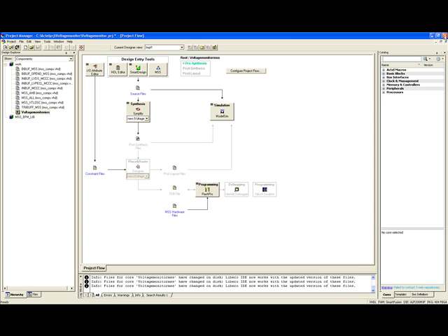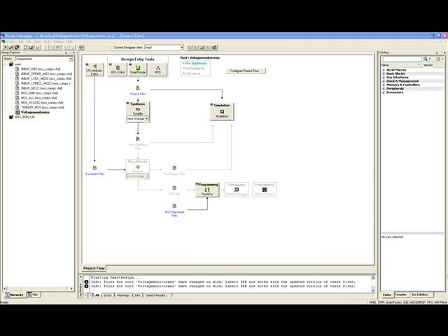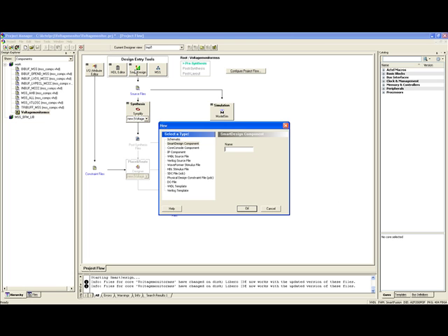Save and close the MSS. To complete the hardware design, open SmartDesign by clicking the SmartDesign button on the Libero IDE Design Flow window. Name the SmartDesign component ACE Top and click OK. The SmartDesign canvas opens.